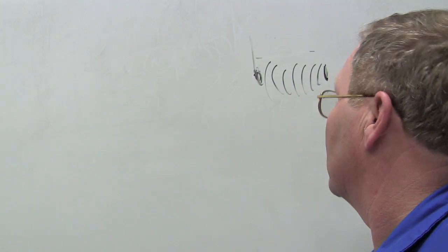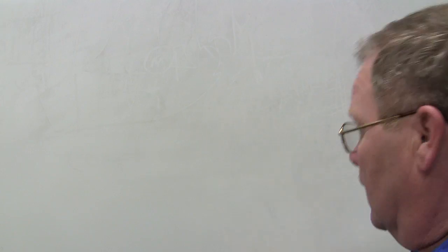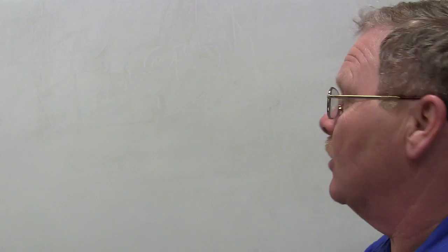Well, I would not call it false air, but that's what these people would call it. Now, is it real? Yeah, that's peculiar. You know what I call it? I call it unmetered air. It's air that's not being measured. It's air that's making it into the engine, but the mass airflow sensor has not a clue it's going in there. And so what happens then?